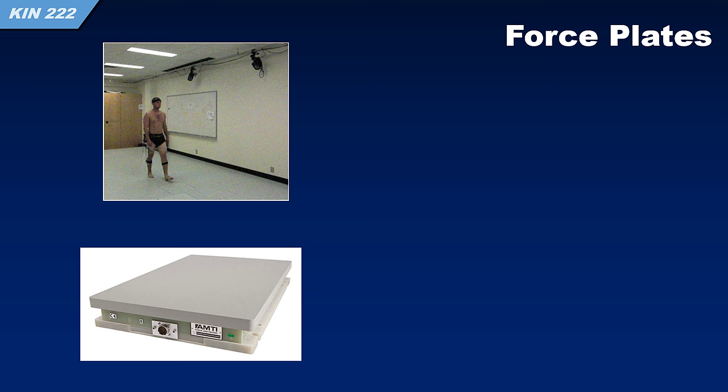Quite often in biomechanics, we'll use a force measuring device called a force plate, which is essentially a bunch of those electronic force transducers all assembled together in a flat plate-like device that's often embedded in the floor, so that when a person steps on the plate it can actually measure the forces that they apply to the ground, the ground reaction forces. Usually the plate is set up so that it can not just measure the vertical force, but also the anterior posterior force and the medial lateral force. This makes the force plate an essential tool in biomechanics.